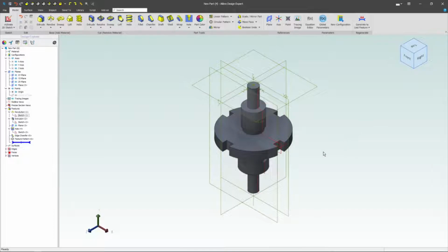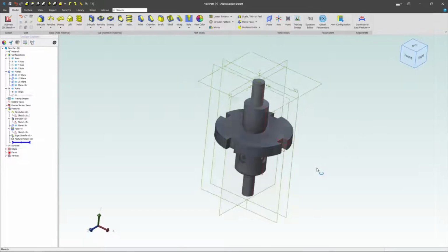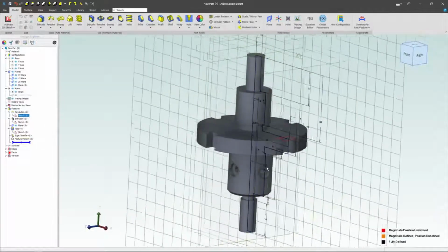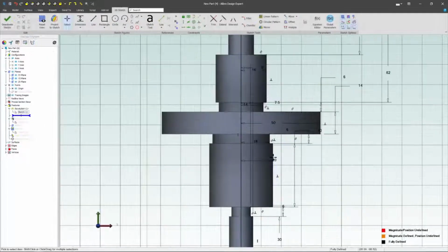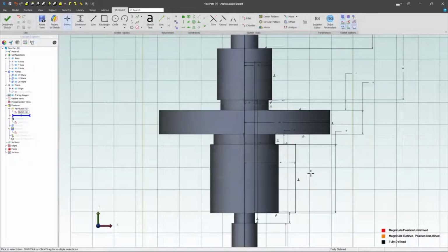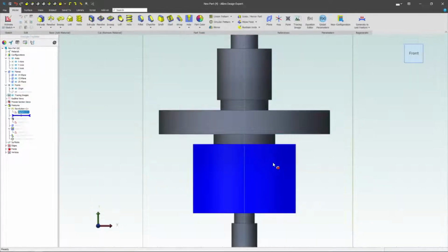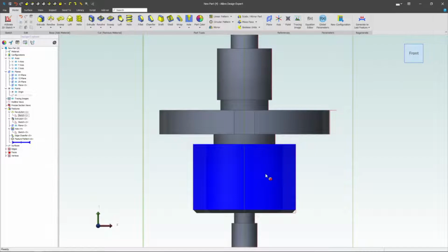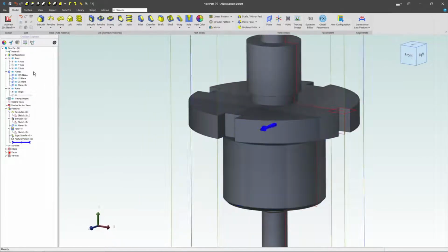So I've got my completed part here. Let's run a few tests on our design intent. Maybe I would intend in the future to update this part so that this would have a distance of 30 instead of 20. If I deactivate my sketch, generate to the last feature, my holes in this surface are gone.